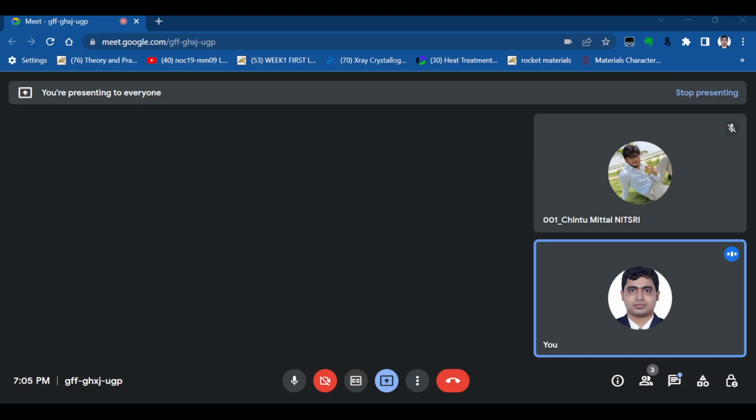No, no. First, read the question properly. On which plane do these two partial dislocations lie? So you have to consider the right side two partials, not the left side one, a by 2, 1 1 0. On which plane the partials lie? That means the two partials, those two you should consider for dot product, and test with each of the options. Which one gives 0 for both of the cases? That will be the answer.